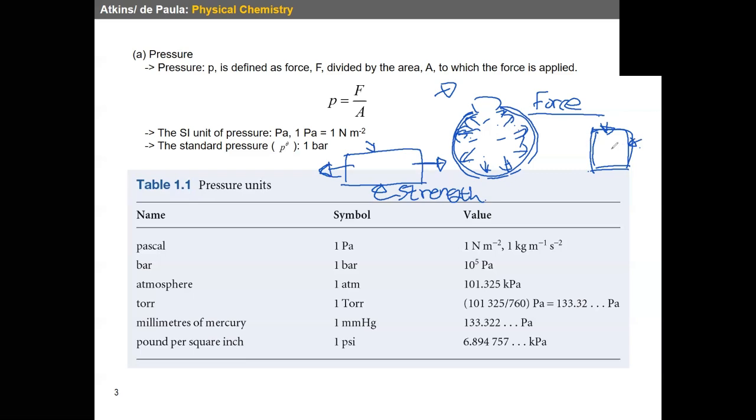So one of the important things is securing high mechanical strength of the material used for the product. That's why people have to test the strength of materials. We calculate the strength by dividing the force applied to the material by the area of the material. Then we have the strength, and the unit of strength is the Pascal.